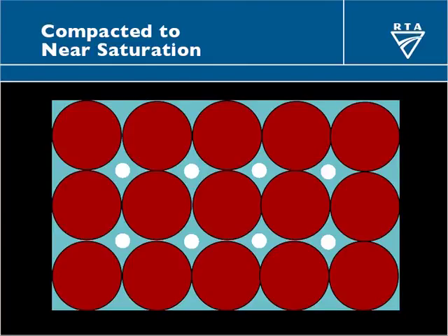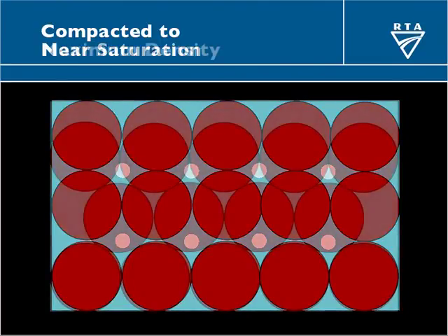And here we have it definitely more compacted. Small air pockets right through it. It's still a fairly loose structure in this case, but it's close to saturation. And if you can imagine that actually being a box, that would be quite stable, provided the sides were supported, but also clearly if it were not supported, the slightest disturbance would cause that to become denser.